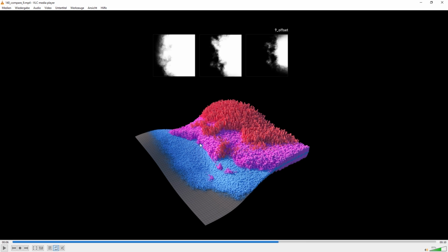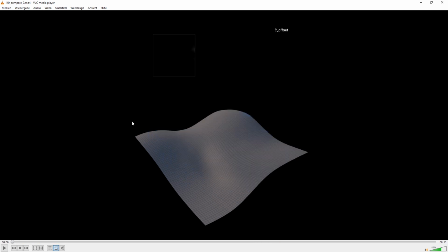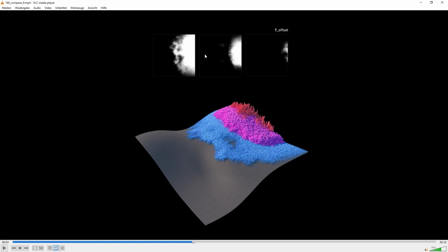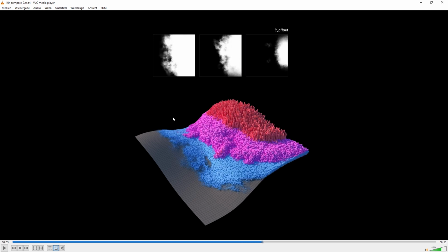The important thing about it is you need to time offset your textures. Each has its own shader effector influencing it with a texture in it, and they basically use the same texture, but they kick in gradually over time. So this starts at 0, the next one could, for example, kick in 2 seconds later, and this one 4 seconds later. By layering in time, by offsetting it in time, you get a gradual growth of your system that is believable. I will show you in detail how this works later.